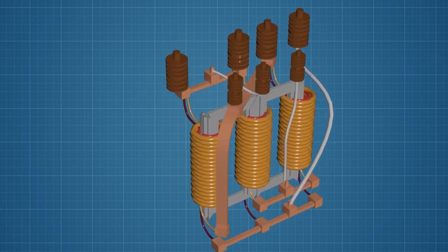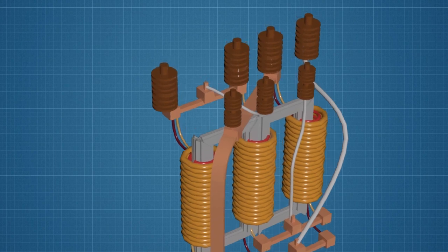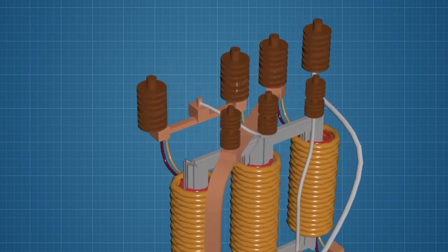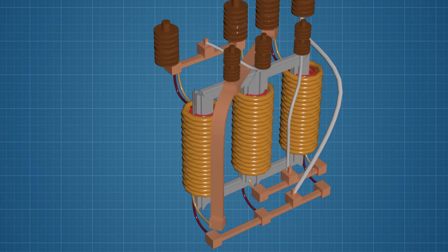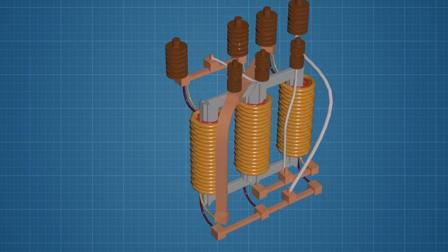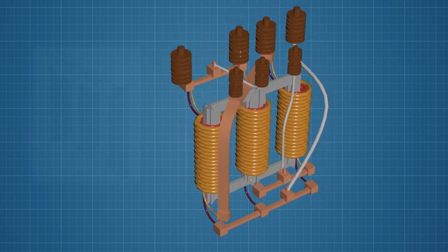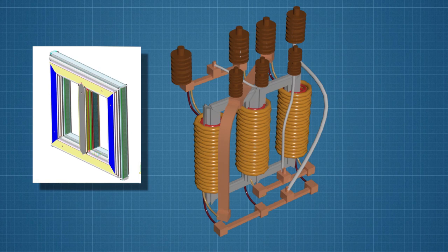Transformer design. High voltage insulators are installed in places where a live conductor shall pass through the grounded metal housing of the transformer. Insulators ensure mechanical fastening and insulation of the current carrying conductor from adjacent conductors. A magnetic core of the transformer consists of rods on which the windings are located, and a yoke connecting the rods into a common magnetic circuit.